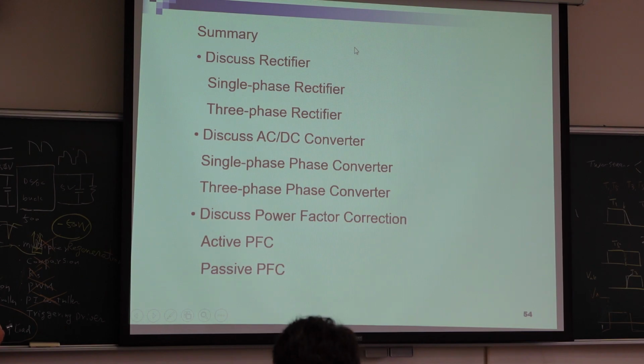So we discussed power factor correction. If you think in terms of the power system, you can go back and think, what is power factor correction? You say, I use a capacitor to remove the Q. So I can put a capacitor, right, to improve power factor. But this is an old idea. Now we use power electronics, so our current is not pure sinusoidal current. Our current has a lot of distortion.